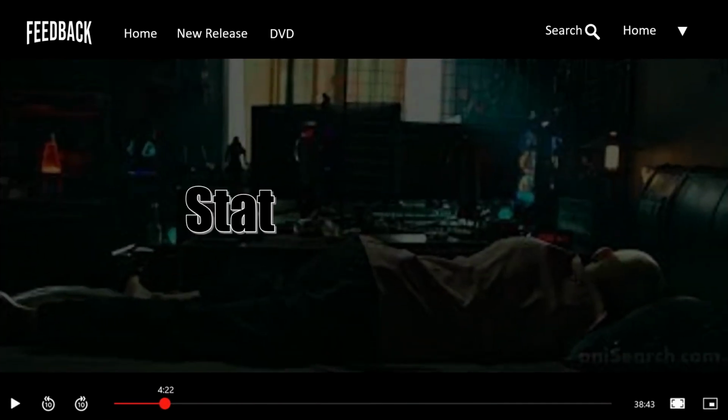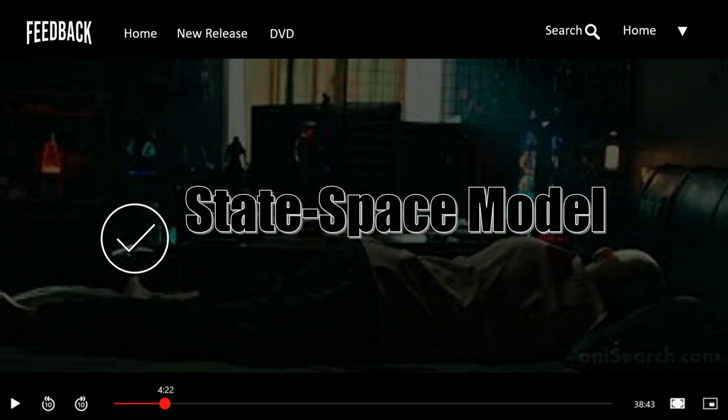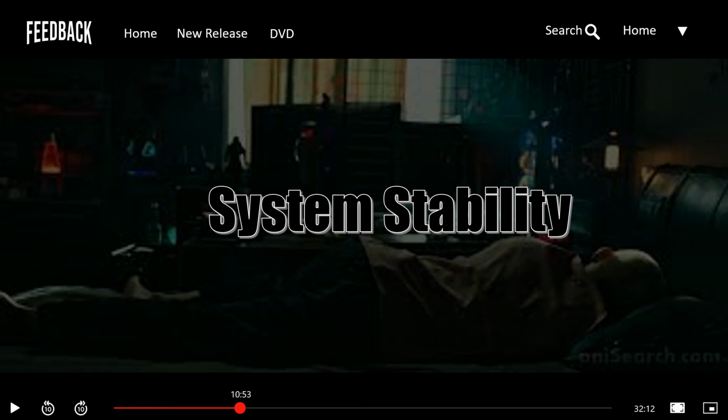As systems become more complex, we discovered that state space representation is the best option because it can be applied to a broad variety of systems. Since it involves simple matrix algebra, which is highly compatible with simulation on digital computers, it is numerically efficient to solve and simulate. Through transfer function and state space model, we can determine the system's stability. The values of the poles and the zeros of a system determine whether the system is stable or not, and how well the system performs.